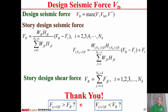And we have two questions for all of you. Is F(i+1)^F always larger than Fi^F? That is, is the seismic design force of the i plus 1 floor always larger than that of the i floor? The second question is, is V(i+1)^F always less than Vi^F? Is the story seismic shear force of the i plus 1 floor always less than that of the i floor? That's the second question. That's all for this lecture.